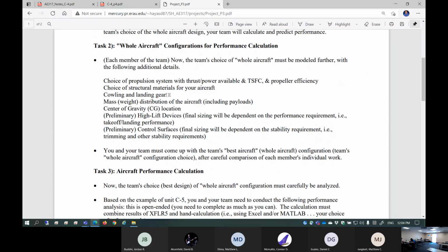And some other constraints such as special thing, cowling, landing gear. If it's manned airplane, you're going to integrate your cockpit block. Heavy lift airplane such as SAE, you're going to specify, okay, this is required payload. You have to integrate those things. Okay? That is going to affect center of gravity location and also neutral point of the entire airplane.